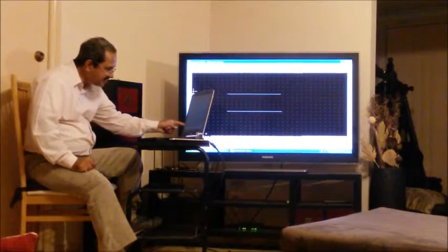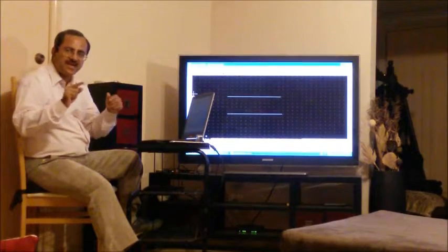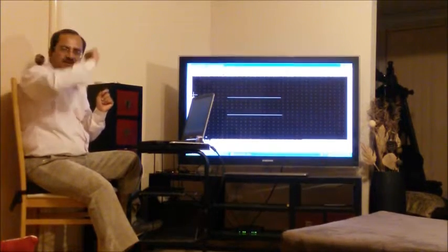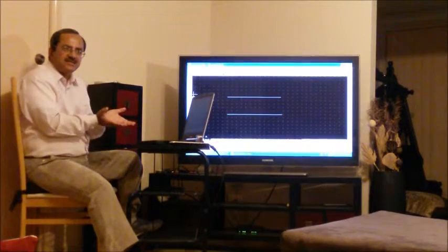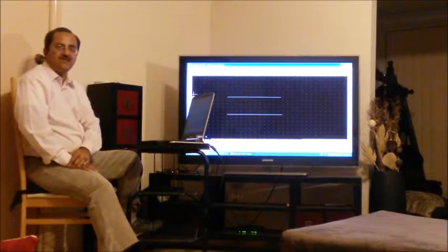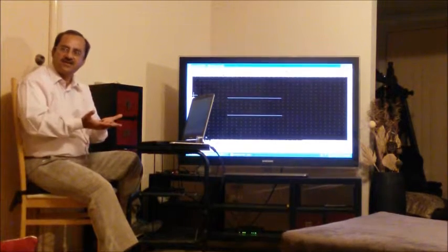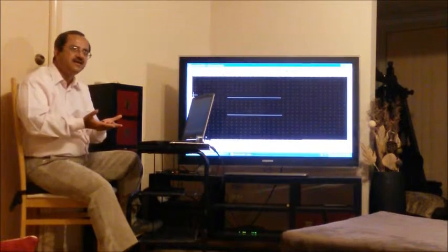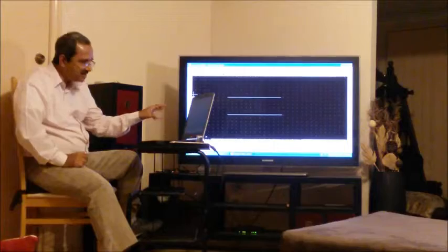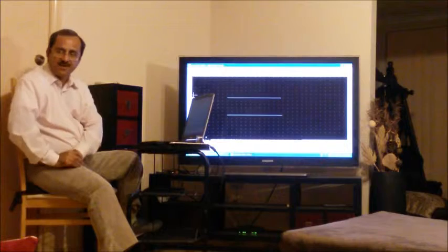And then there are, in the square brackets, other options also. Whenever a square bracket is given in AutoCAD, that means if you don't know the center point, but you know the 3 points, for example. It's asking me the center point, which I don't know. So what to do now? These other options are now available. So if you want to give 3 points, you type 3P. Instead of asking center point, it will start asking first point, second point, and third point. So these square brackets are the alternative options which are available to us.